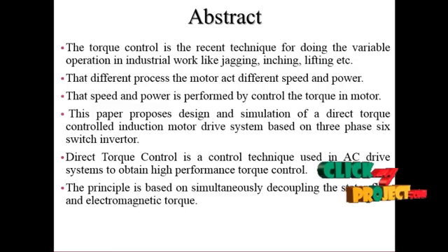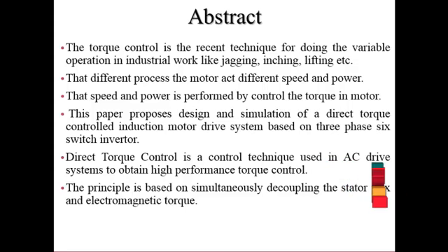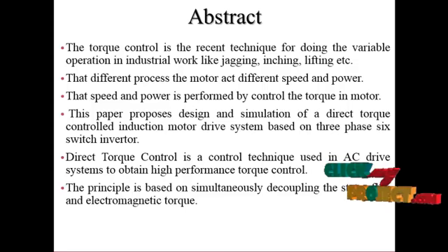This has been achieved thanks to a suitable combination of the 4 unbalanced voltage vectors instinctively generated by the 4-switch 3-phase inverter, leading to the synthesis of the 6 balanced voltage vectors of the 6-switch 3-phase inverter. This approach has been adopted in the design of the vector selection table of the proposed DTC strategy, which considered a subdivision of the Clarke plane into 6 vectors.